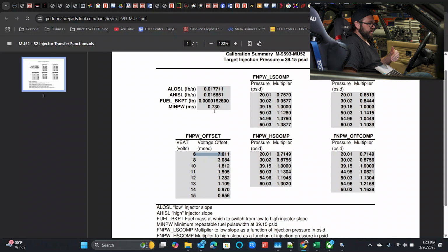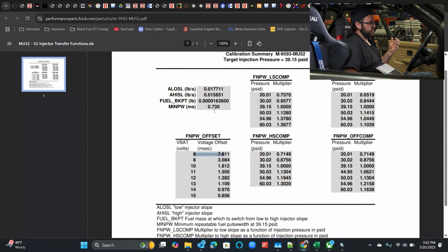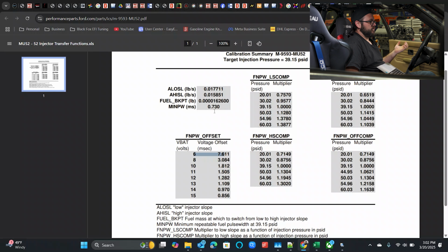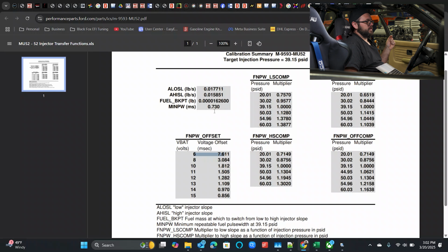That data I do not calculate from this sheet. So if you're using something like Fuel Injector Clinic injectors, they still do the injector data in the 1.5 values, but you can import that data over, and the small pulse width section there is still correct in the 1.6 firmware. So again, small injector pulse widths only really matter when you're using a very large injector on pump gas or race gas on a small displacement motor.